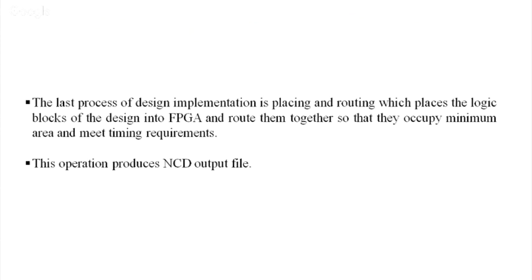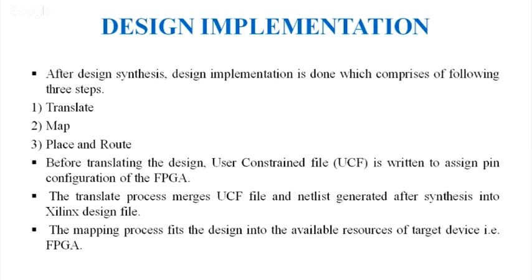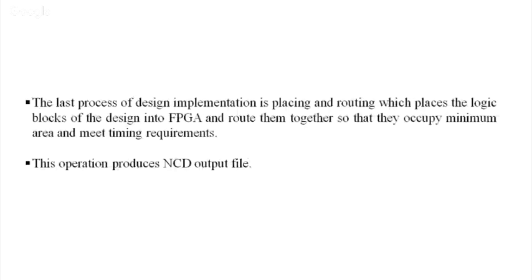The last process of design implementation is placing and routing, which places the logic blocks of the design into the FPGA and routes them so that they occupy minimum area and meet timing requirements. So for a very large area of FPGA, a very small amount of area is covered by this mapping, place and route process. After that, this operation produces an NCD output file.